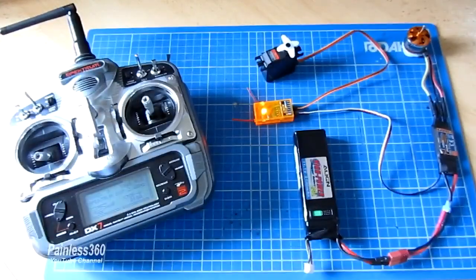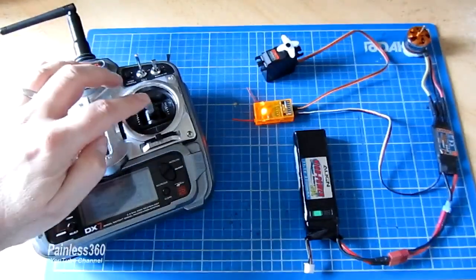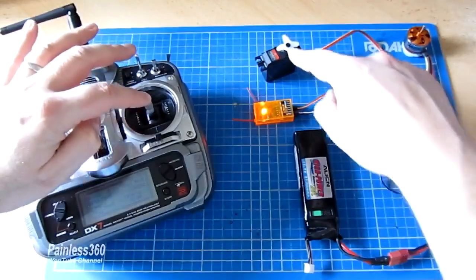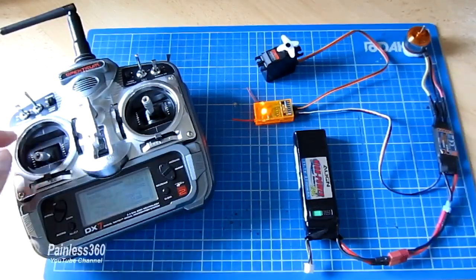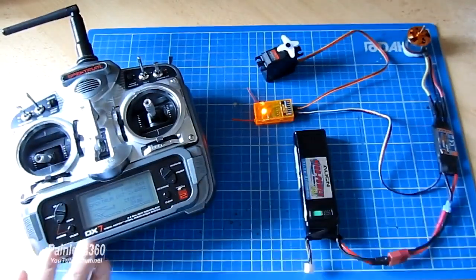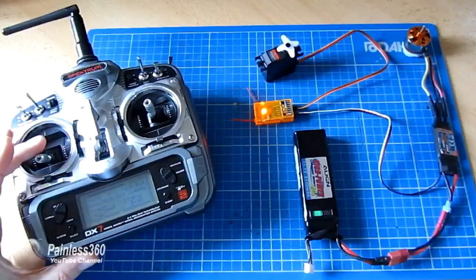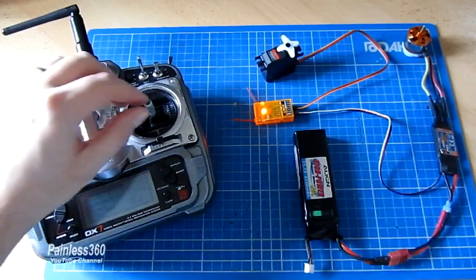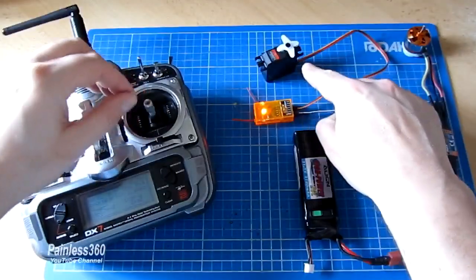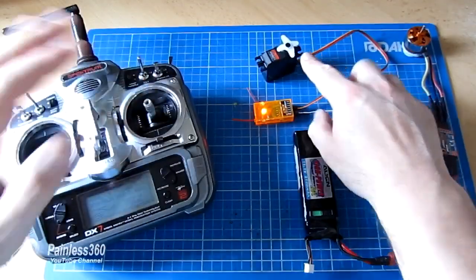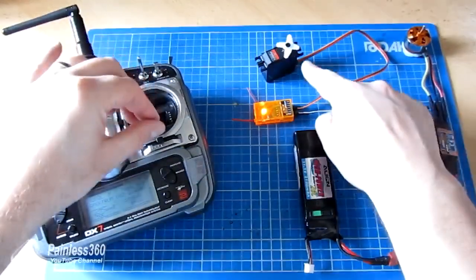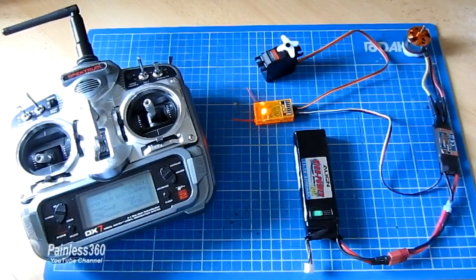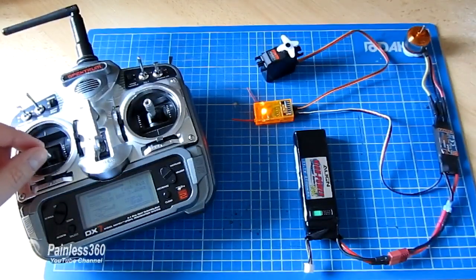You'll notice that all that's really happening is the radio is translating the movement of one of the controls into the movement of either a servo or the amount of throttle that goes into a motor. And that is all the radio system is doing. All of the other fancy stuff on a computerized radio, the menus and everything else, is all about how those two interactions work. How much you have to move the stick to move the servo. How much the servo moves at each end of the stick movement. But very basic principle, as you move the stick, you move the servo, or if it's connected to a speed controller, the control will look after the throttle.